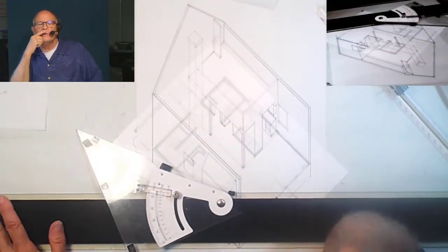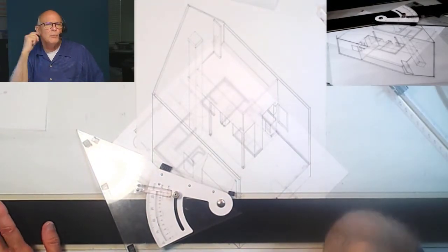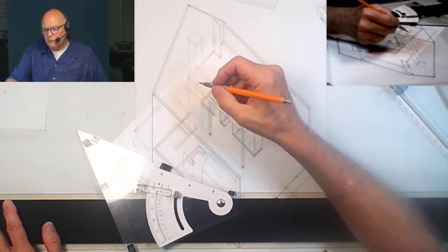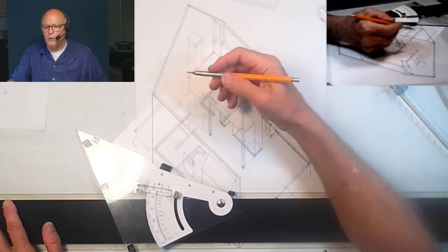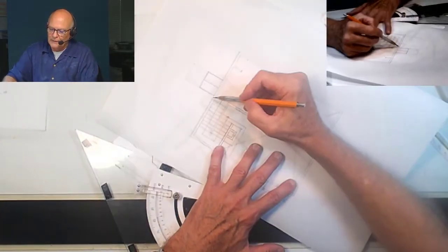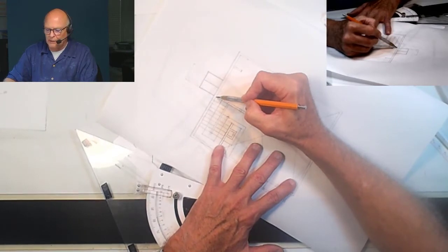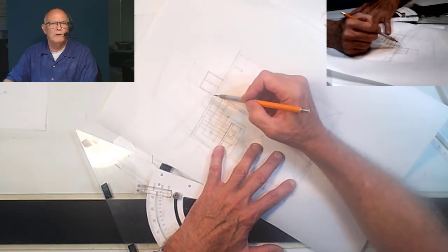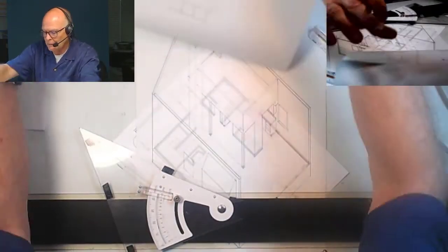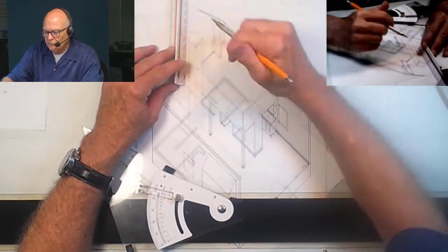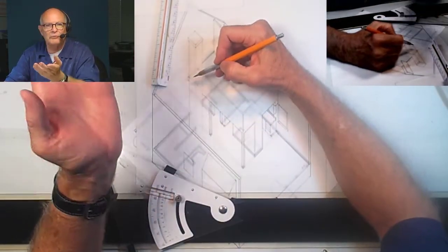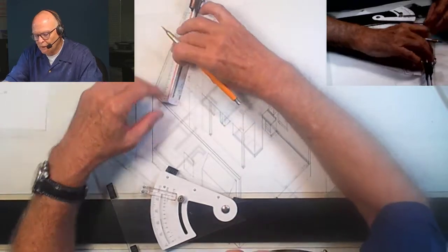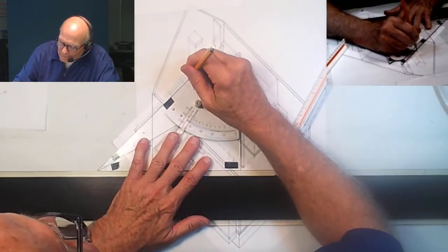So how are we going to do those stairs? We don't have to do them all like we did last week, but we do need to do some of them. And that's going to give us that slope that we need. To do that, if we start at the very outside where we took our measurement, we start on this point and measure down 7, out 11, down 7, out 11 for each of those, going maybe 3 or 4. We don't have to go all the way down because it's not necessary, but that's going to give us the information. So if we're coming off, this is the first step. We're going to go down 7. So we're going to mark it. And then I'm going to come out 11.